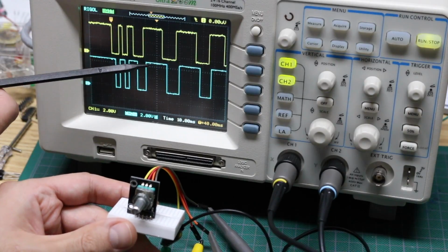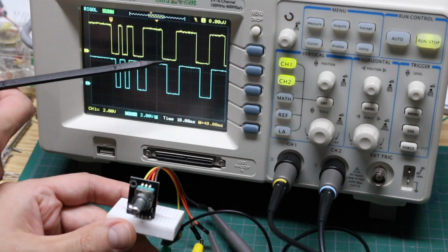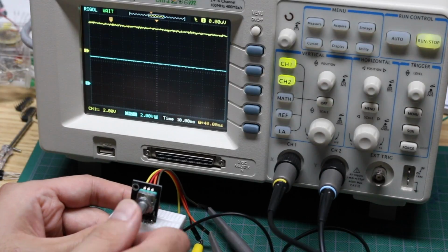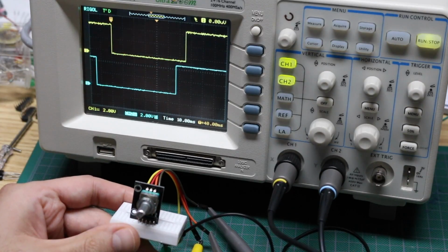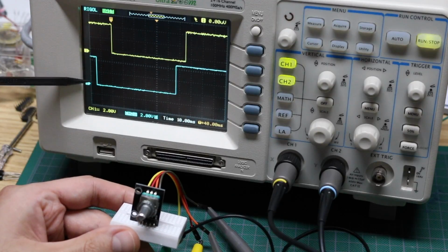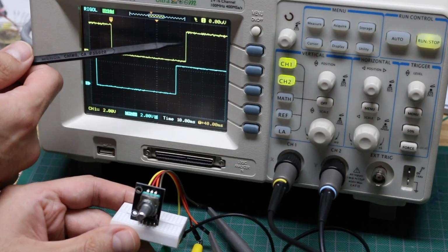So here, when they're both high, it's idle. Then it caught another rotation and I was going clockwise. A goes low, then B, A goes high, then B goes high. We're idle again. Going counterclockwise, that was a good full screen slow move. So counterclockwise, they were both high, which is idle. Then B went low first, followed by A, and then B returned high, A returned high.